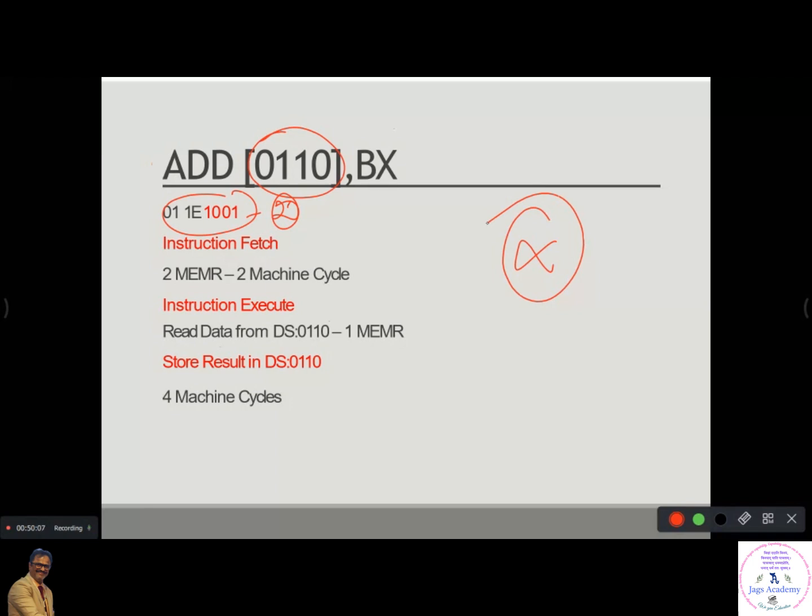Try to understand it. This is very important. Questions are going to come on this. And it's very easy. 100%. Even first standard students can do it. Suppose if there is a segment override prefix, you have 67, 66. How many machine cycles are required now to read the opcode? 3. That's all. It all depends on how big your instruction is. Understood now? Okay?